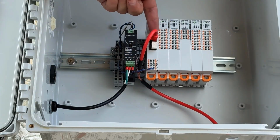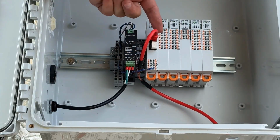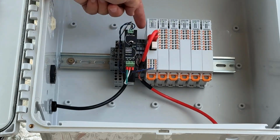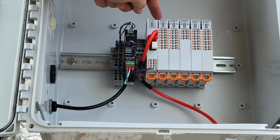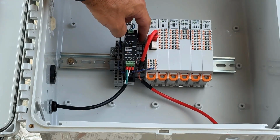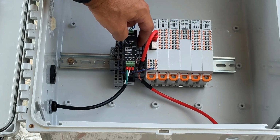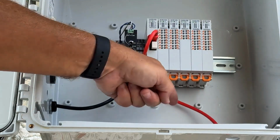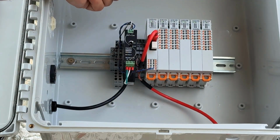And we have got this pigtail of an RJ45 patch cable that we cut off and also connected to the field terminal strip. So in this case, again, just using traditional field terminals, we need 3 of them, one for CAN high, one for CAN low, and one for V minus in order to go with this approach for category wiring all the way through.